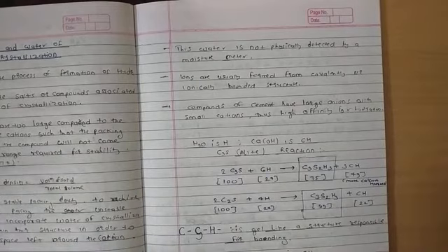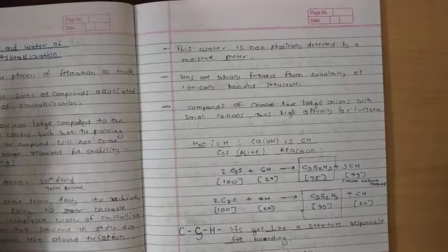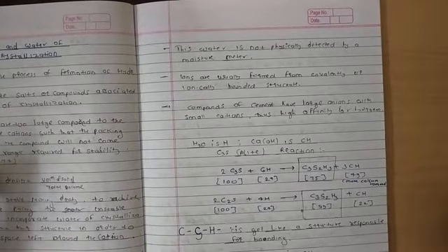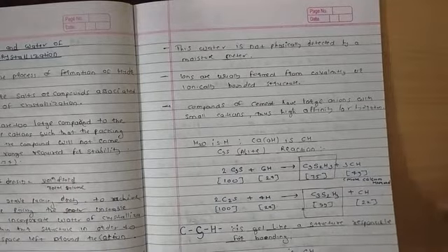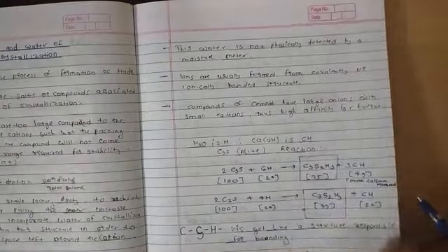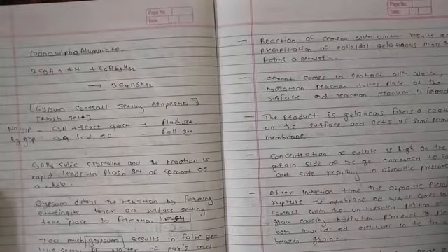It is a very complicated formula with many variables. It depends on the temperature, the atmosphere, the wind velocity, the type of admixture, the type of component, and pozzolanic or mineral admixture. It varies, and there are several variables present in that formula. So, ignoring that formula for ease, we write it as CSH gel. It is a gel-like structure formed after the hydration process, and it gives the cement the property to hold its ingredients tightly. Is it okay? If you don't understand, please pause your video and record this.